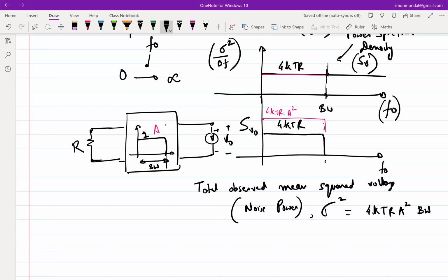Okay. So that is one of the reasons. In principle, you can always use an amplifier of infinite dB to amplify anything and should be able to observe it. If somebody talks at the other end of this world, in principle, I should be able to put an amplifier and hear it sitting in this class also. But you cannot, because there is noise, right? And the noise in the channel will be suppressing the signal. And if you amplify, you are going to amplify both noise and the signal. As long as the signal that is reaching you is not higher than that of the noise, you cannot do anything.